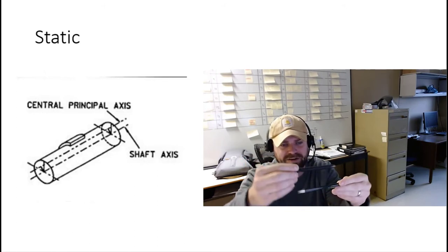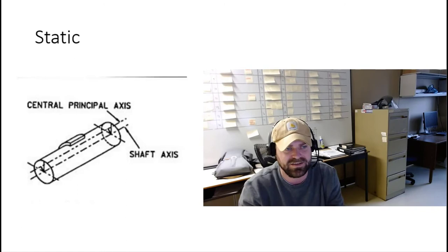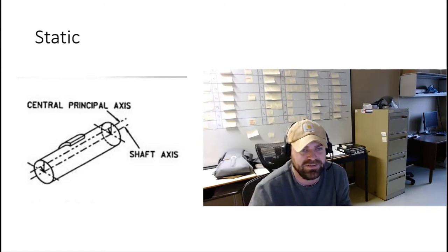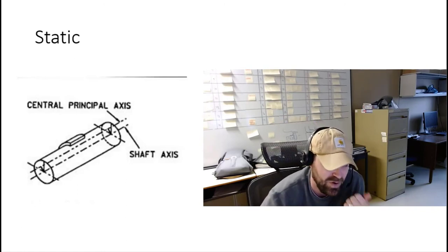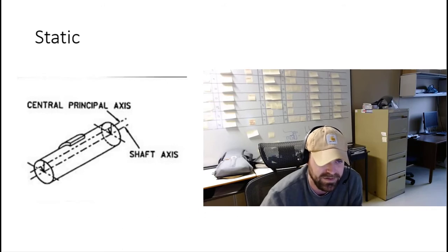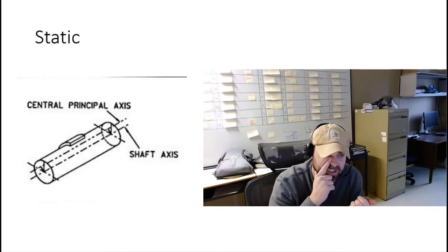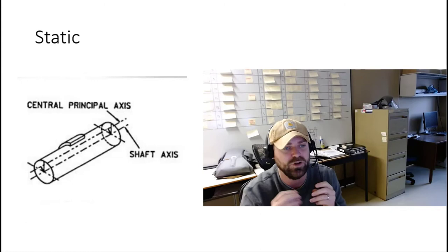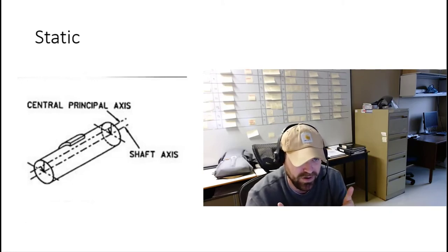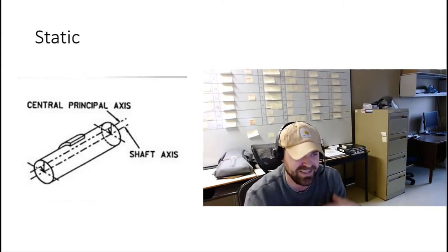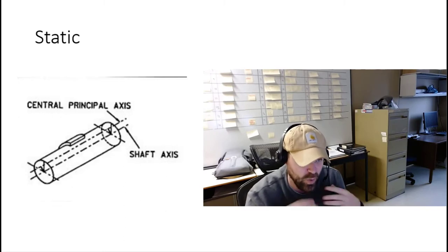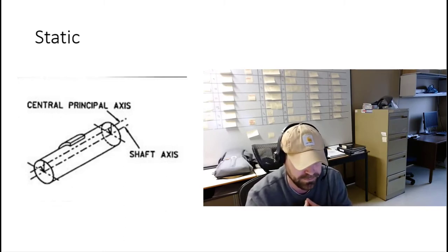There's no angle there. It's just displaced. So that's what static imbalance is. This type of unbalance is also called force unbalance. Static unbalance can be pictured as simply one heavy spot located in the center of the rotor, which acts to displace the center of gravity of the rotor away from the rotating center line.